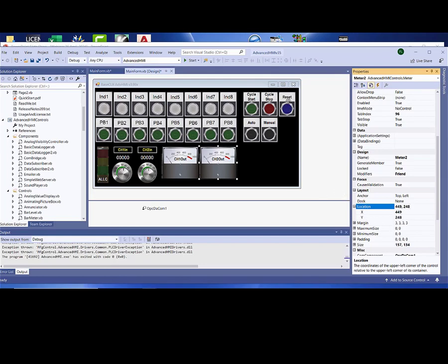Okay, so in principle, that's what you would do. In a standard HMI, FactoryTalk View, something like that, that's a pretty easy thing to do, because you take wherever you put that object as 0, and then you say, okay, here it's at 0, and then I drag it over and I say, here it's at 100.